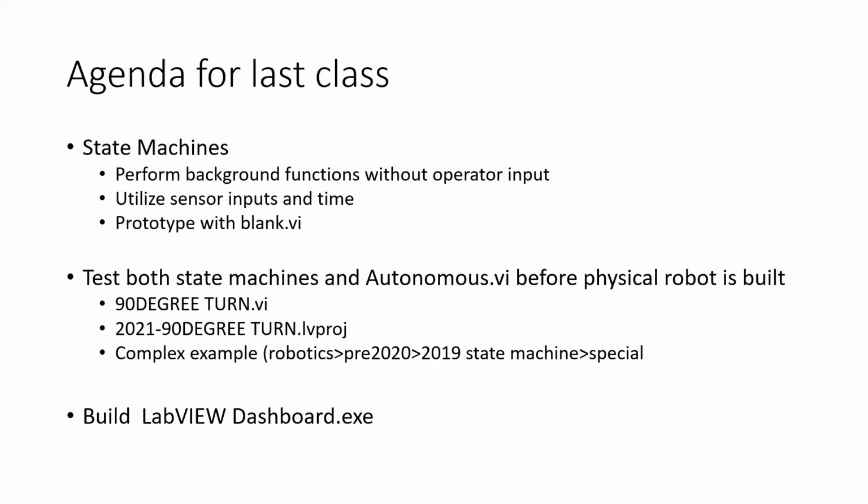Virtually any vending machine, any microprocessor-based design or system is run by a state machine. And while there's certain qualifications for what that means, it basically doesn't have somebody telling it what to do. It's running autonomously, and that program is embedded in the non-volatile memory of the processor.